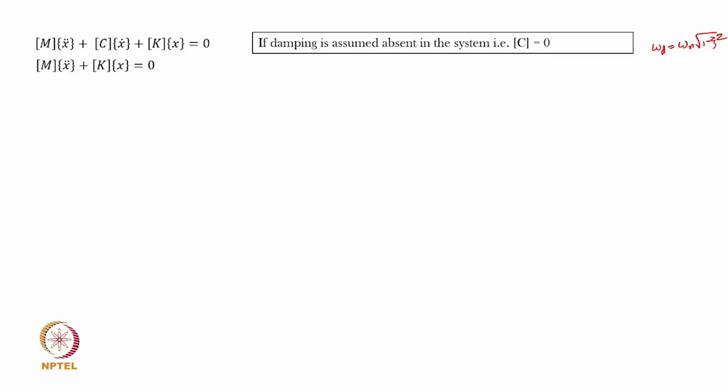Okay. Now, zeta, typically for mechanical systems, unless you intentionally put in a very heavy viscous damper, most of the time, whether it is structural damping or even damping using a dashpot, zeta is going to be a fraction, and the square of that fraction, and then the square root of that whole number, is all going to be indicative of the fact that omega d is very close to omega n, quite close.